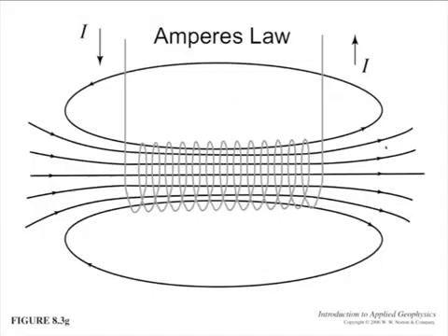All right. So then, according to Ampere's law, if we have a current that's twisting around the loops of this coil, this current I, then we're going to get straight lines of a magnetic field. Okay, it's the same cross product operating there. Here is a standard inductor, a coil operating in free space. It's going to be generating these magnetic lines of force, which, since there is no such thing as a magnetic monopole, come around back to the other side of the coil, even if they have to go to the other side of the world to do that.